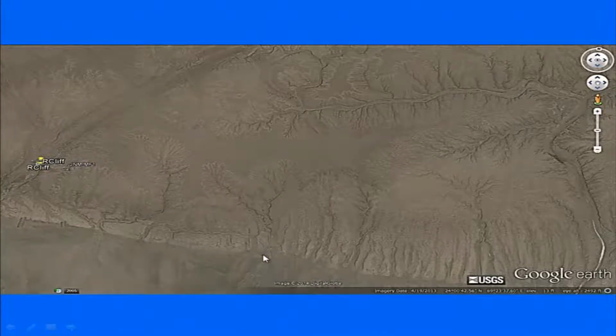And here, if you see what we were talking about, for this channel here, these are all sub basins, and finally these are also some basins which are contributing to this channel and then meeting the trunk stream, and this will be the base level for this channel. The base level changes, and since there is a change in the gradient here, that is a geomorphic divide, this portion has resulted in the formation of smaller deltas.